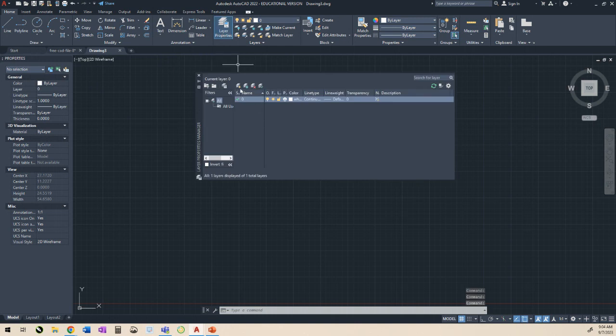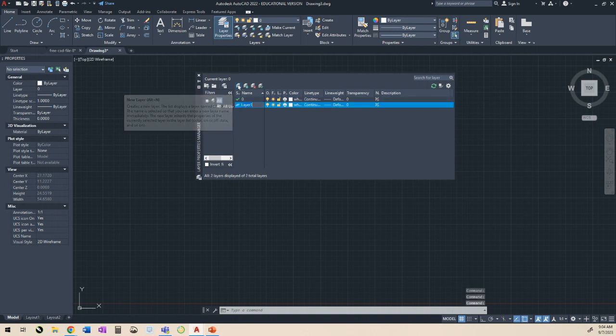And if we click on this sun, sort of star-like icon, it's going to give us a new layer. So we're going to add a new layer. We're going to use a standard by making our layer titles all caps, and anything that's annotated will start off with the abbreviation ANNO. So these are annotative dimensions. And if I hit enter, that name is now selected.